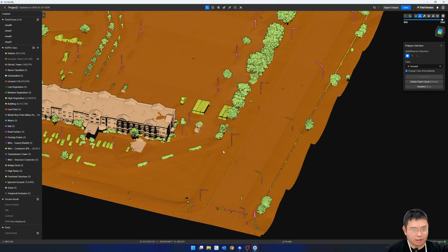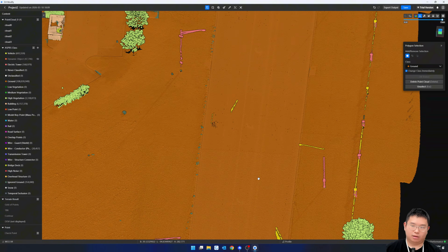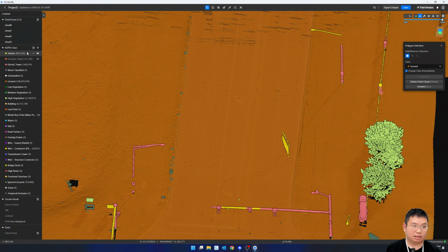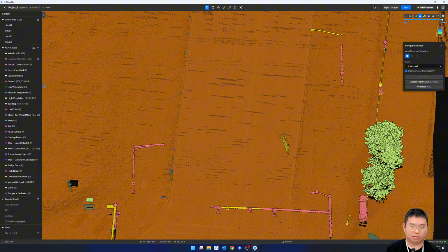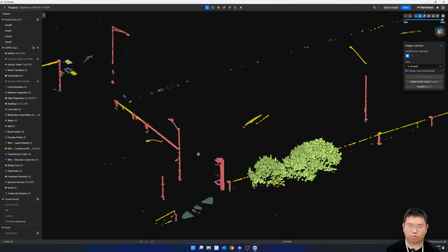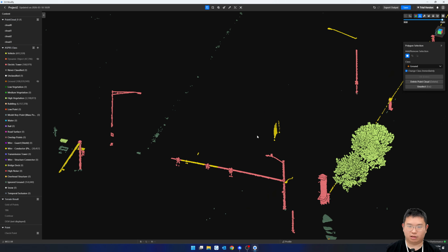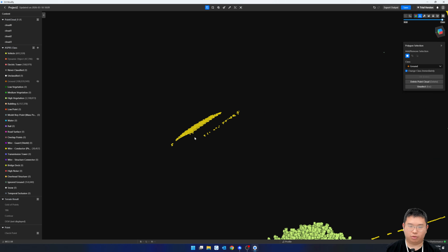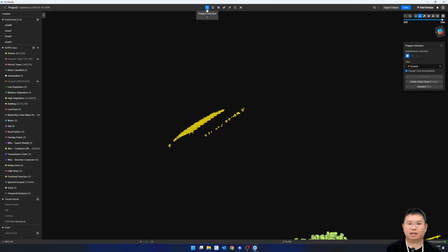So within the modify software, we can select hide ground points, right? So now our ground points are gone, leaving us with these floating points. So we're going to select the first selection tool to show you. That is our polygon selection. Basically, you just need to create a polygon, and any points within that polygon will be selected.